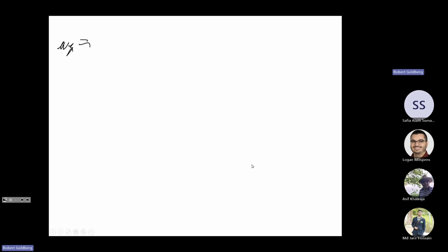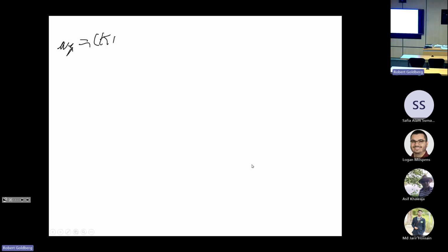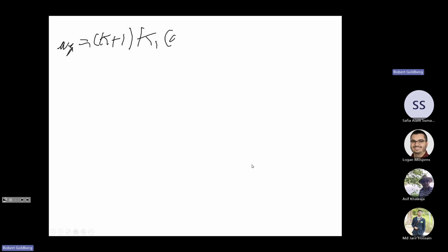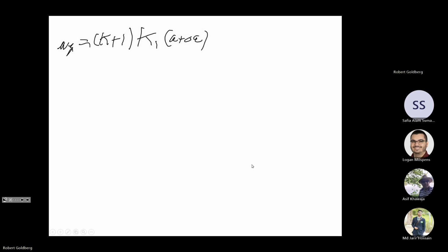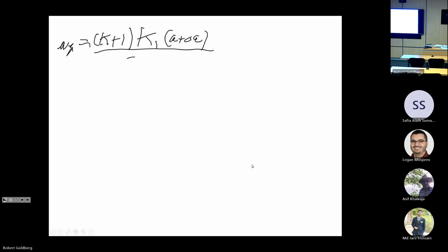So when we do all of that, and rearranging things just a little bit, what we have left is our displacement in the y direction is equal to kappa plus 1 times our stress intensity factor measured at the original crack tip, A plus delta A. So we're talking the stress intensity factor at the original crack tip before we applied any of these closing stresses, divided by 2 times mu, which is the shear modulus.